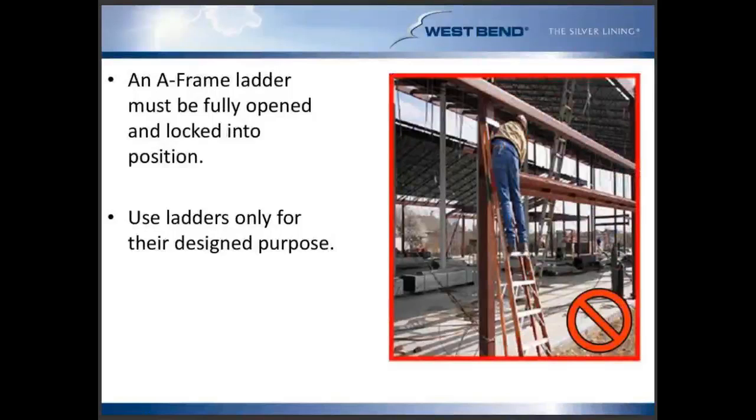So an A-frame ladder or a step ladder or self-supporting ladder, whatever type of term you want to use to call these, the old rule of thumb is making sure that we don't collapse them and use them in a leaning position like you can see in this picture. Again, that's not using that particular ladder for its design purpose. They're not intended to be used this way, and you run the risk of that ladder slipping out at the feet and sliding down and causing the employee to fall.